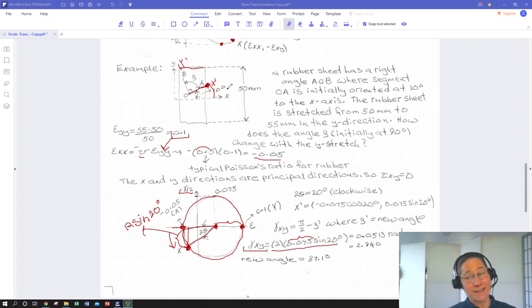So basically, that and the relationship between those 2 points and the circle center gave us our circle center, gave us our circle radius, so we had our Mohr circle. Next most important point was to say, okay, where is the rotated x-axis on our Mohr circle? So for that we use the 10 degrees counterclockwise relationship between x and x prime direction, so that's our theta angle on the part. We found that on the Mohr circle using 2 theta on the Mohr circle equal theta on the part.